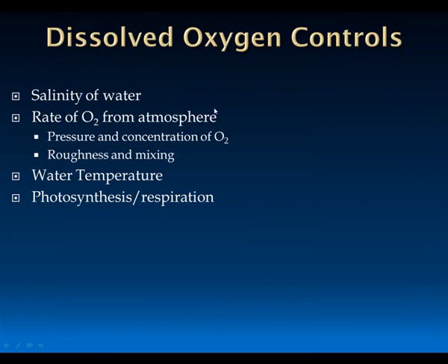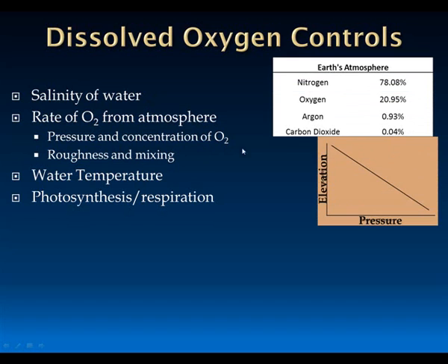So thinking about the controls on dissolved oxygen in streams, salinity is important, but as far as freshwater goes, the salinity is so low that it's really not important compared to the others. If you're talking about seawater, then salinity would be important. The rate of O2 coming in from the atmosphere, which is both pressure and concentration of O2, and we can